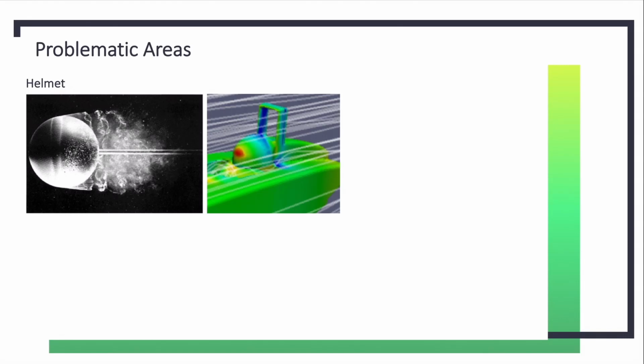So let's have a look at the flow characteristics around it. And you can think of a helmet a little bit like a sphere. You have flow coming onto this sphere, travelling around the first half, front half, and then separating around about the midpoint. Now, when you have fast air around the outside of it, up here, this airflow will start to turn and you will end up with vortex shedding occurring off the rear. And that creates really chaotic flow and will in turn induce drag.